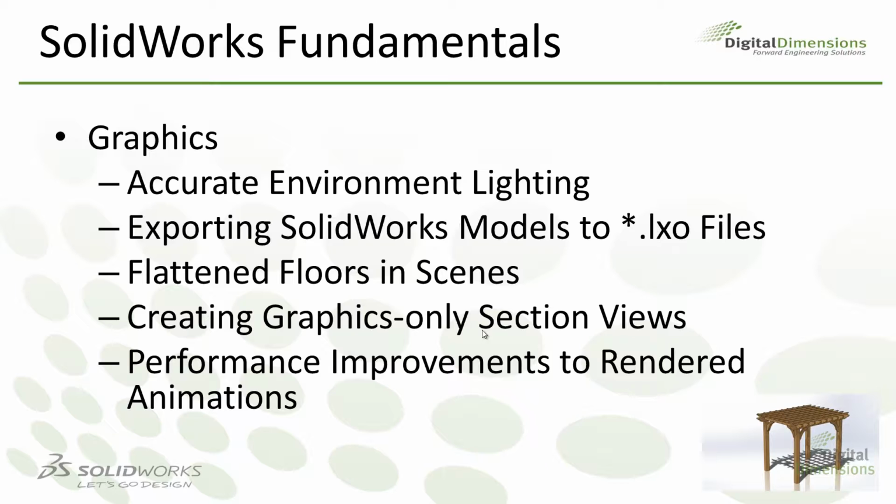And you'll just see it in the Save As menu. Flatten floors and scenes, I'm going to actually show you that in just a moment. That's a neat option for scenes for PhotoView in 2014. Creating graphics-only section views, we couldn't do this in previous versions. You could not create a graphics only section. You also could not create a section view of a surface model, which we can now do in 2014. So those are enhancements to section views. And then lastly, just some general performance improvements to rendered animations that should make rendered animations much faster.